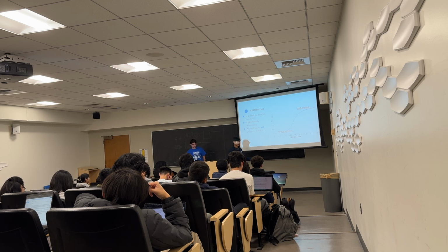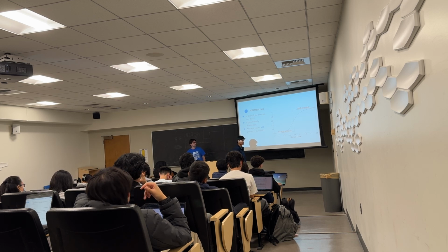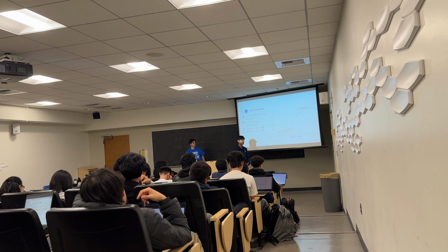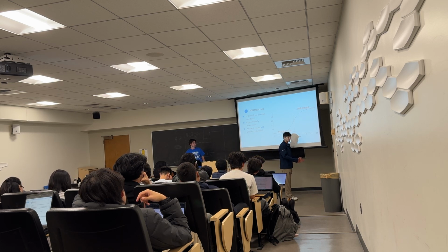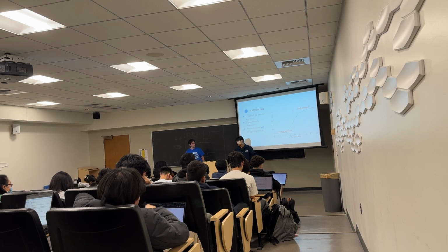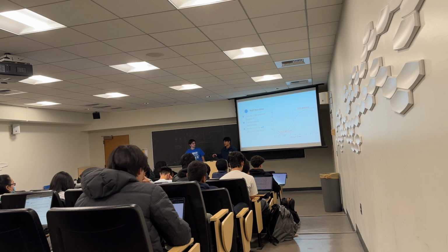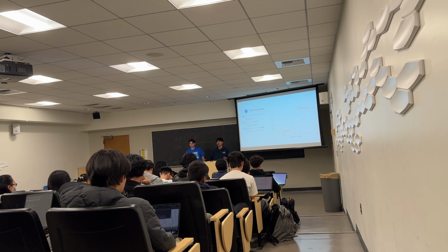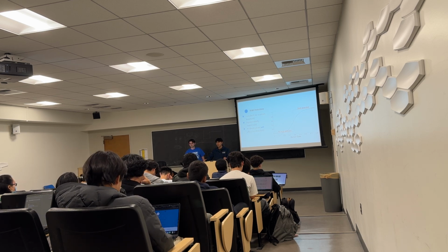You can still detect a wall from a distance, say this is my wall, you could detect a wall right here, but when exactly do you want to turn? So you set a threshold: once I'm this close, then I want to turn, so I detect a wall at this value. It's going to be a lot of values that you have to see to decide when you want to turn. How are you going to know the distance to the wall though, or do you just set the threshold at 10?